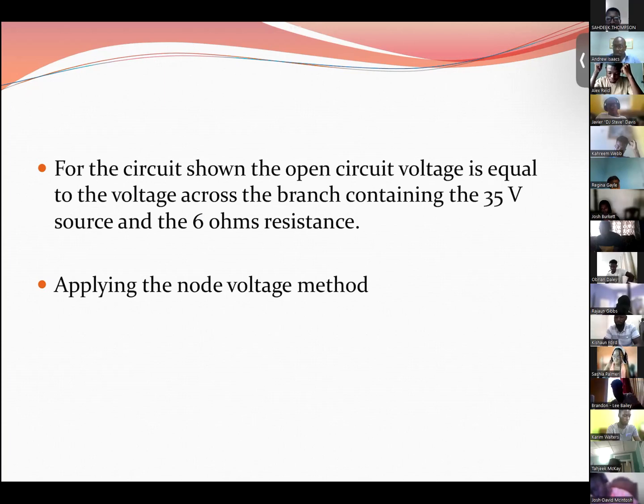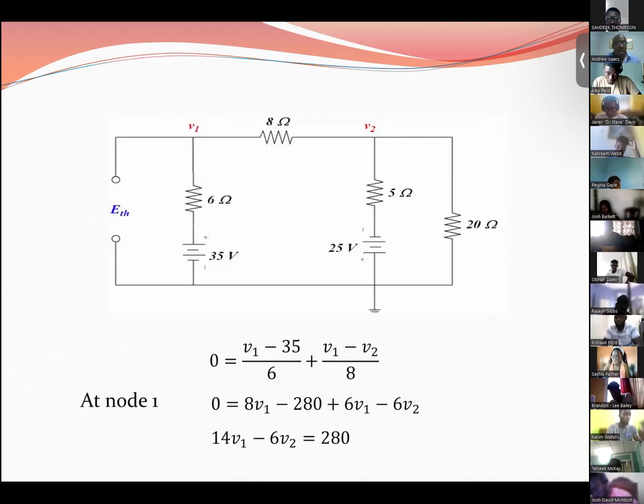So in doing that, I identify our nodes. Now, students, last week when we looked at nodal analysis, one of the things I said is that the principal nodes that you consider would be those where you had current division. So in this instance, you would have considered just one node. For this network, you just have one node that you would consider as principal node.